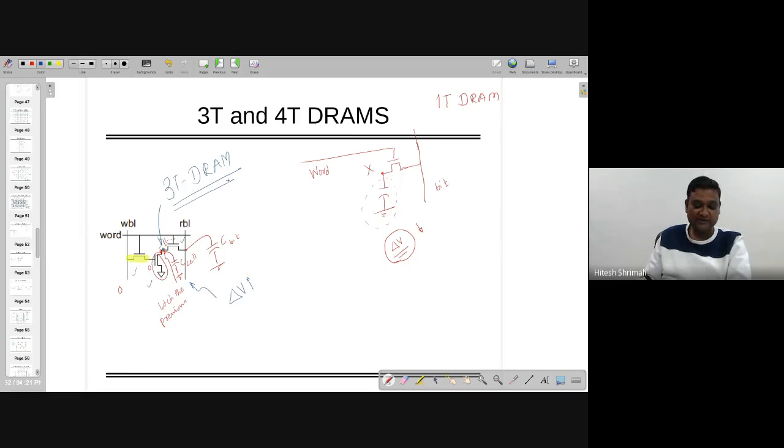You need to analyze in such a way that you know which particular node is important for you, and accordingly find out the value of the W by N. You can think about it like this: when there are two access transistors A1 and A2 and there is a driver transistor over here, you need to find out, for a given driver transistor, which one has to be more or which one has to be low. Note that all three transistors right now here are all NMOS. So there is no usage of PMOS over here. So accordingly, you can see,